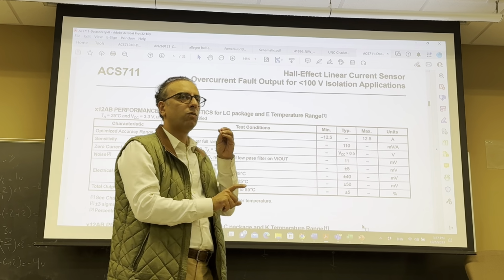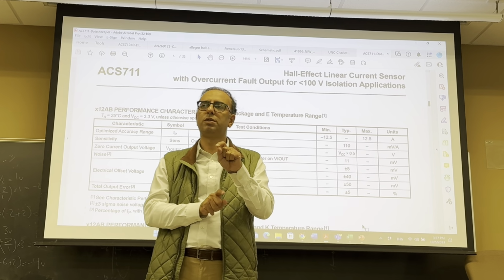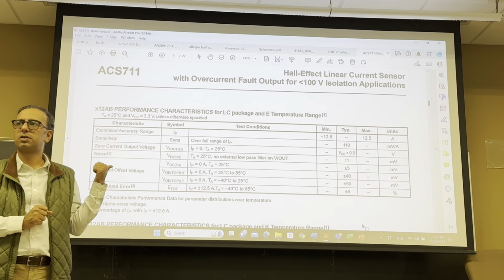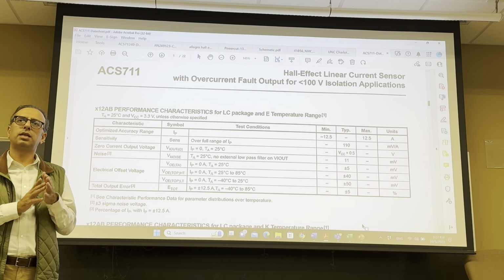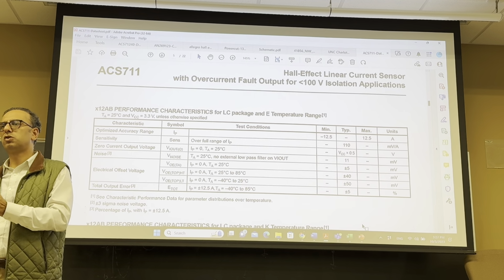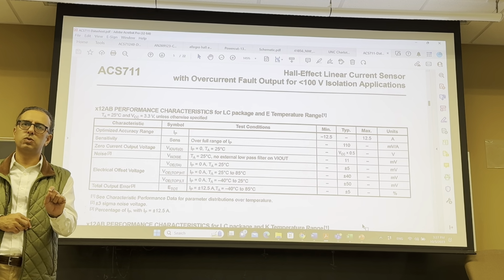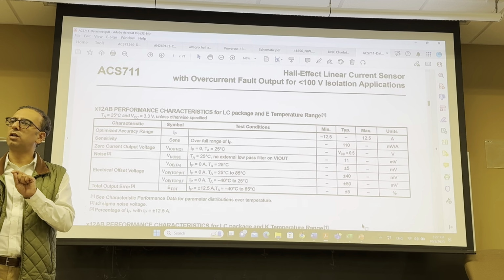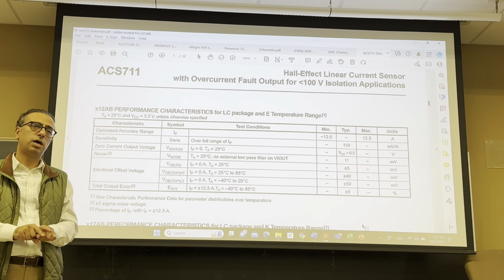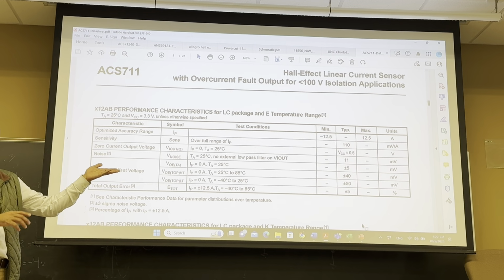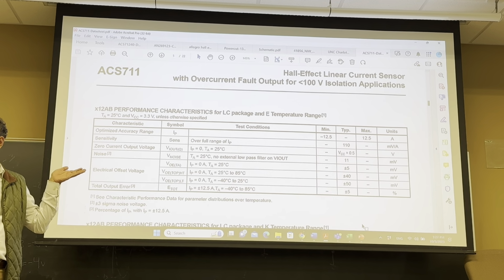But depending on what component you choose and what conditions you're applying, in this case, for instance, you're seeing that your op-amp functions best with 5 volts, right? Not 3 volts. And you don't want to use a regulator. So you have only one bus of 5 volts in the system. Then you have to come up with this conversion.